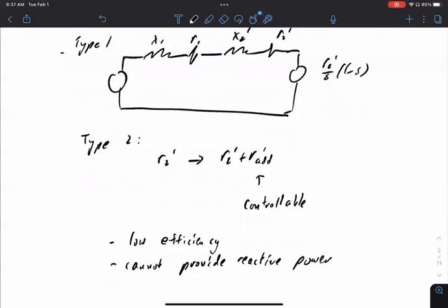There's no wind turbine where you add a capacitor inside this generator circuit. Does it have to be really big? The capacitors would have to be really big, so it'd be expensive. Right, so capacitive elements are bulky and big. If you look at the capacitance value per size of the capacitor, it's really big. So to cancel out this inductor, you need a fairly large capacitor. And having a controllable capacitor inside the rotor is not doable. You need an air gap, you need isolation, you need a pretty big bulky capacitor. So that's too hard to do.